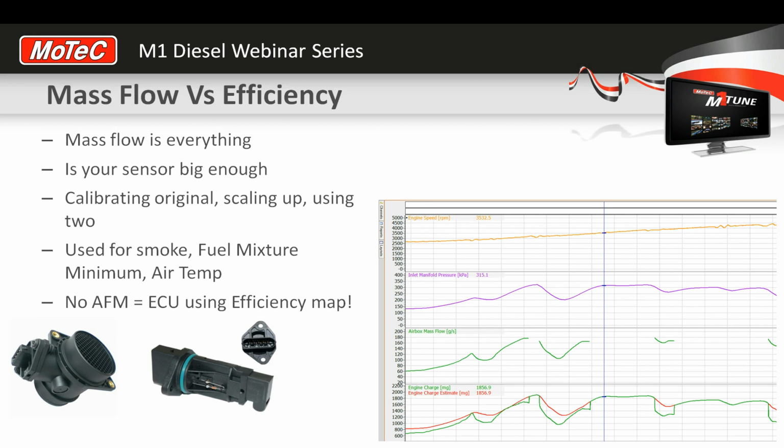And that pedal percentage table, of course, is called the nominal fuel mass table. So if it was dead linear, with 0 at the bottom and 100 at the top, at 50% pedal we'd be asking for 50% of our fuel. And if we had 100 milligrams in our fuel mass limit table, we'd be requesting 50 milligrams of fuel.